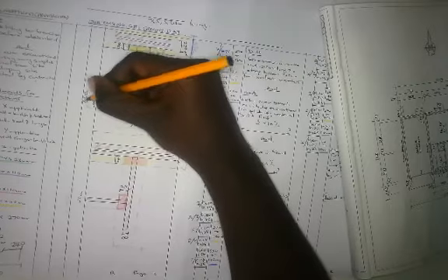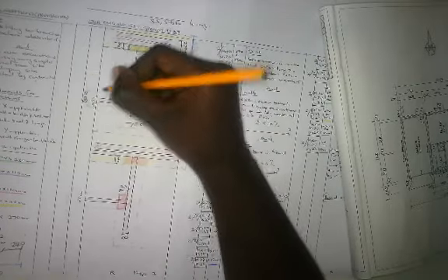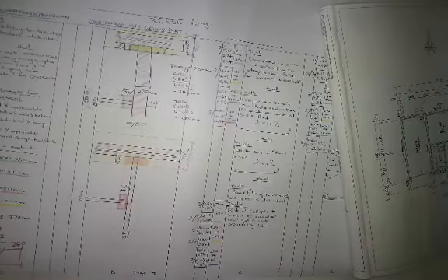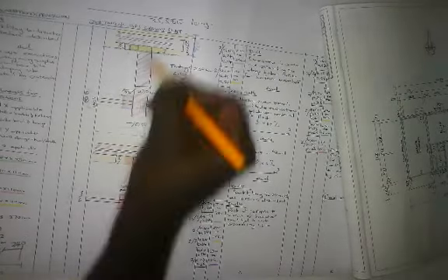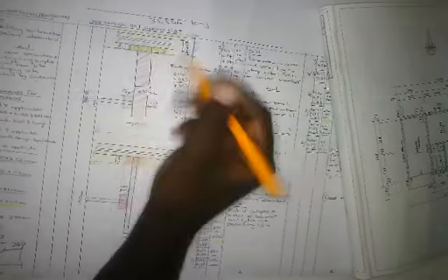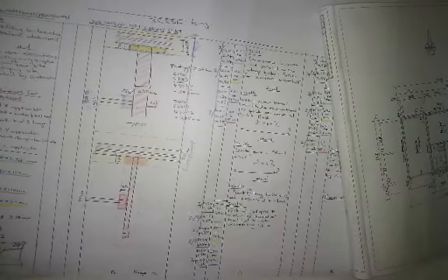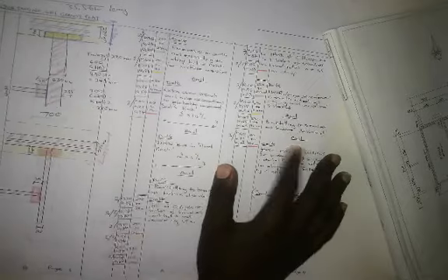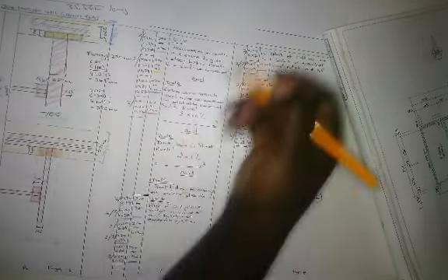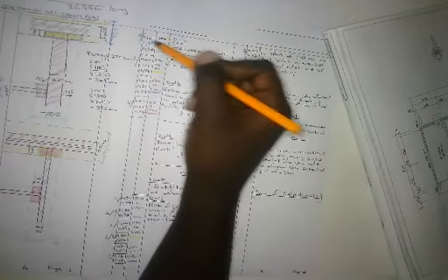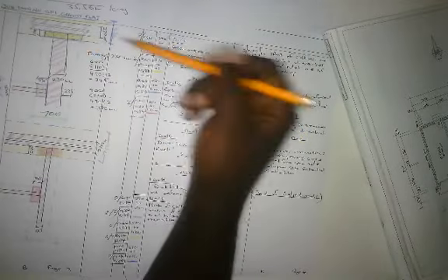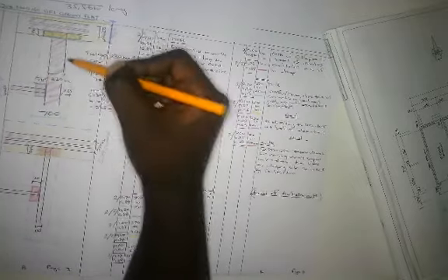So from here to here is 235 also, and from here to here is 235. 235 plus 230 plus 235 gives you a 700 wide trench, okay. So we're gonna say 235 times 600, which is the width of our 110. Our 110 trench is 600. 600 by 235 by the depth of our trench, because we're deducting for the trench, because we are over-measuring if we take this right through.